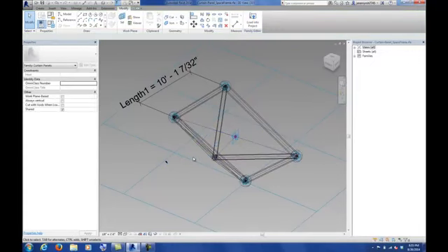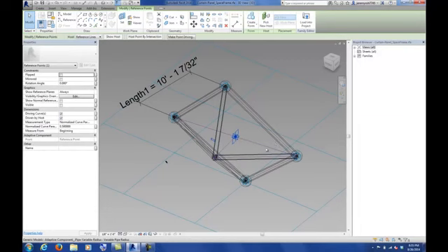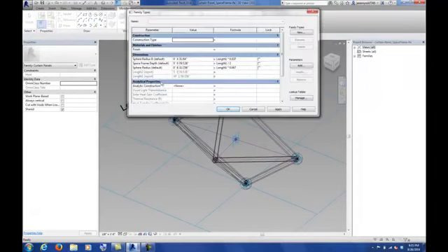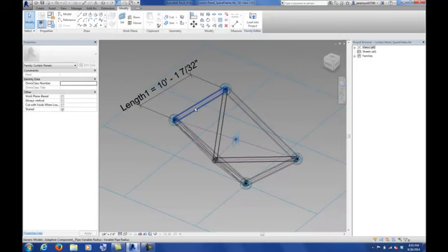So what I'm going to do is just hit delete. These points can't be made into adaptive points because we're not in that family. Remember, we're just in a curtain panel pattern-based family. For the dimensions I'm going to utilize, remember at the end of class I made this one length 1 times 0.037. This radius is always going to be smaller than the other spheres around it, because these spheres are probably going to be a little larger, if you look at the way the layout works. And these pipes are a little bit smaller.